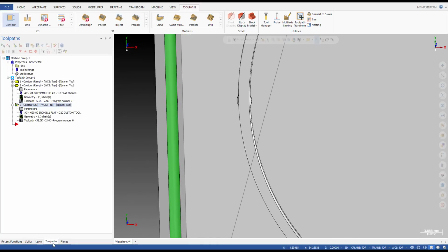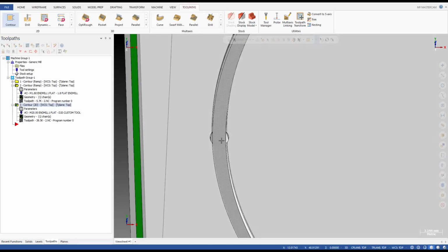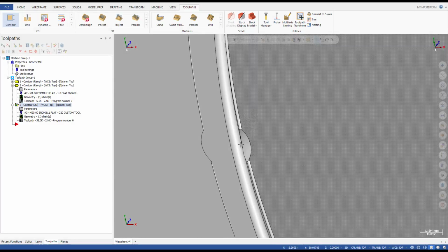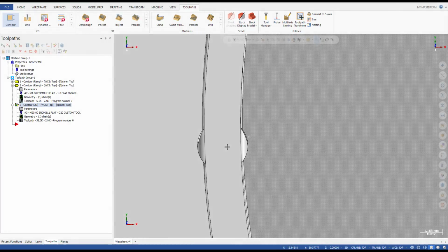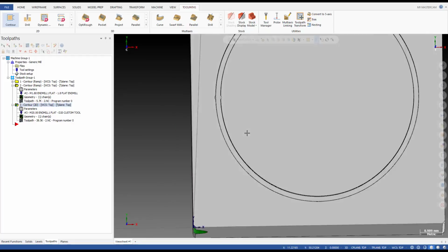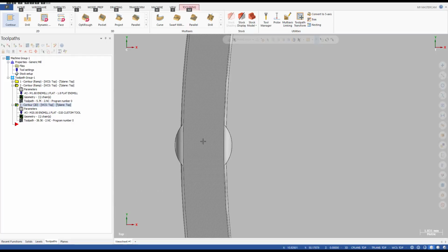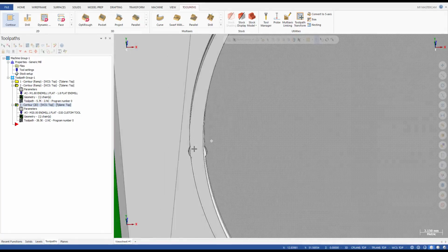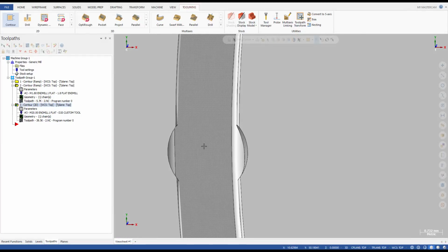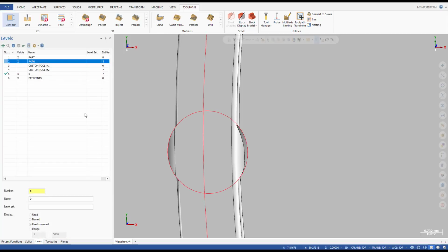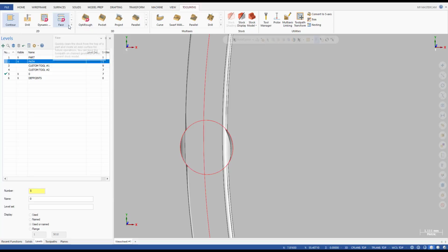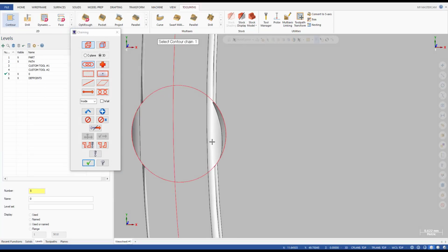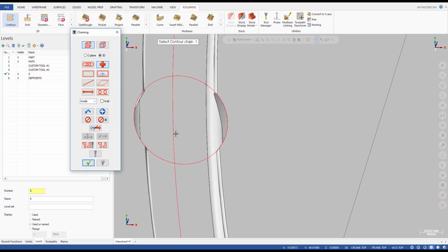This role has a drop hole here, so it allows you to drop the dovetail cutter here and do the contour. Okay, I will turn on the part level and part. Okay, and we do some contour, select some entry point, and then I'm gonna select the contour.